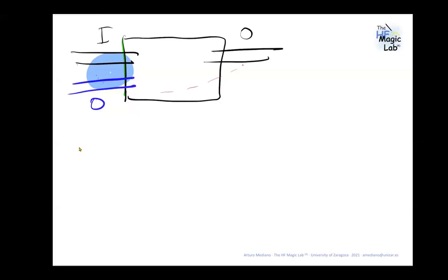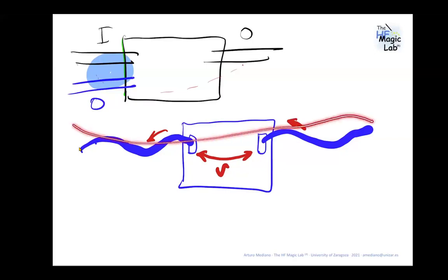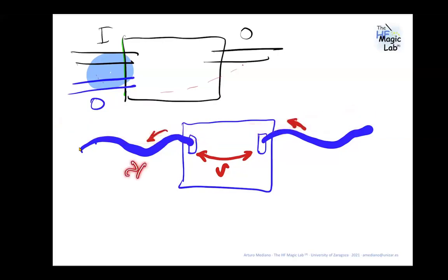But be careful, because in some situations, if you put the input connector here and the output connector here, and this is the cable, what you can be creating, this is dependent on how you do the layout of the PCB, is the possibility to excite a dipole with this voltage, okay? If you create a dipole, you will have a current going from left to right, from right to left, and at the frequencies where this is lambda/4 and this is lambda/4, you are creating something close to a parasitic dipole.